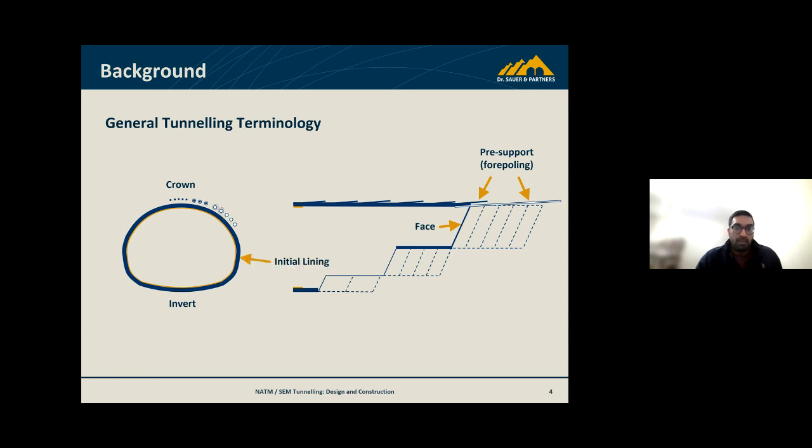And then the linings, which is what we use to construct the tunnel. The first lining is called the initial lining. If you have a large enough cavern or tunnel, you have separations and temporary walls and temporary inverts, basically taking smaller chunks of the tunnel out before creating the full larger structure.